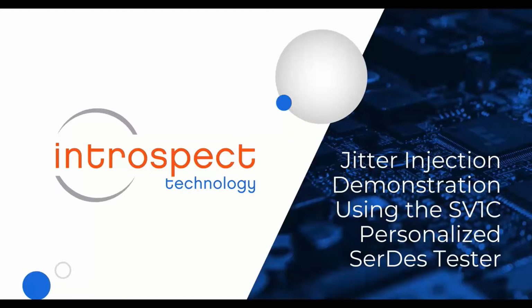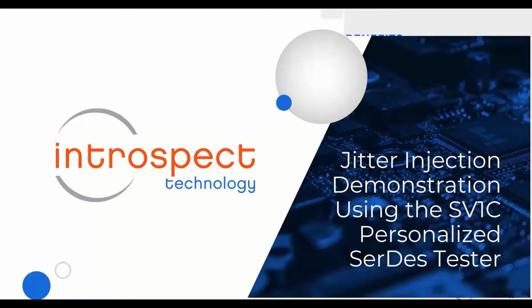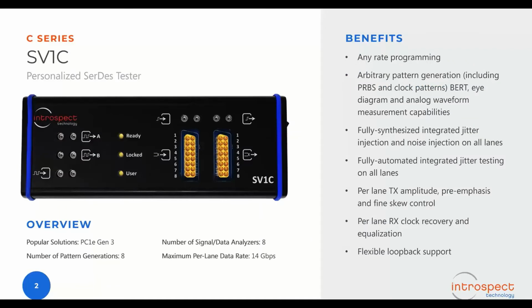To begin, here's a quick overview of the SV1C Personalized SerDes Tester product that we'll be looking at today. The SV1C is an 8-channel test system. It has 8 pattern generators and 8 BERT detectors, and it's capable of arbitrary pattern generation. It also has fully integrated jitter injection on all of its lanes. The setup for today's demo is shown here.